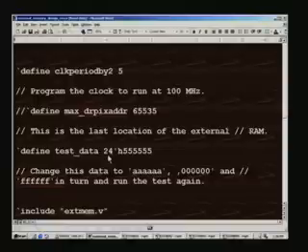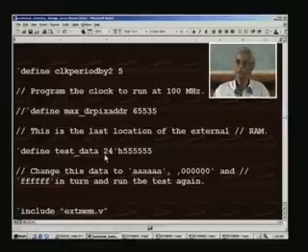This RAM is 24 bits in width. This is because we need it for video scaling, and we need to process 3 colors for the motion picture. That would demand 3 bytes, that means 2 hex digits for red, another 2 for green, and another 2 for blue. If you want to test some other data pattern, you are free to do so by merely changing this. For example, you can change it to all As, or all zeros, or all FFs. I suggest that you take them in turn and check this.